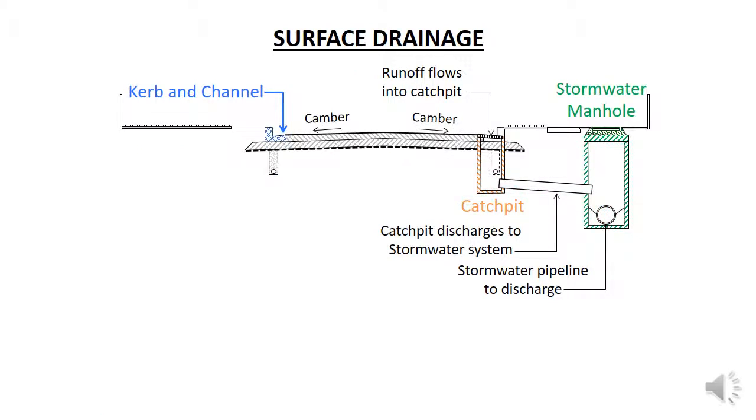The surface drainage system collects and disposes of rainwater on the surface of the road. Water on the surface of the road lessens the friction between the road and the tyres of the vehicles on the road. This lessening of friction results in less force resisting the sideways, otherwise known as lateral forces, that a vehicle exerts when changing direction.